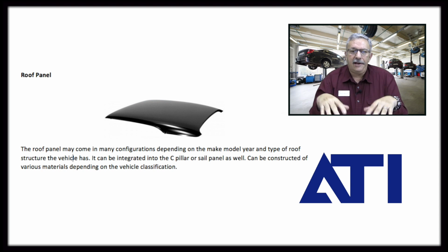I'm going to talk a little bit more about welding processes later, but that's important to know because I've got to take the headliner out. I've got to make sure that both airbag systems are disconnected, isolated, and removed. And that's an important step in making sure that I put the vehicle back to pre-loss condition.